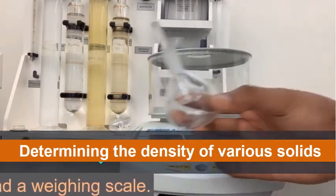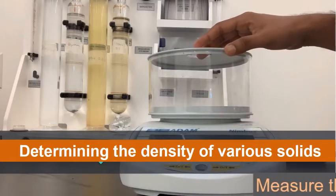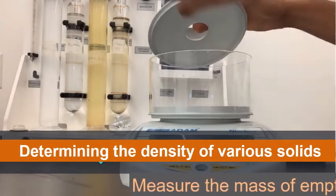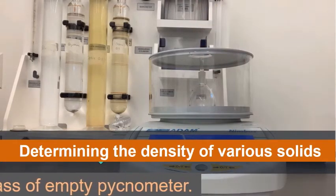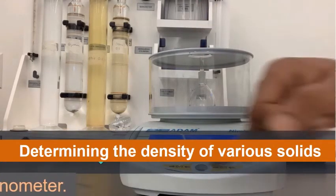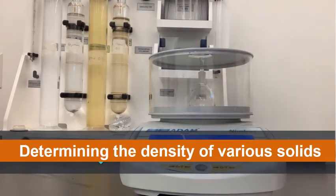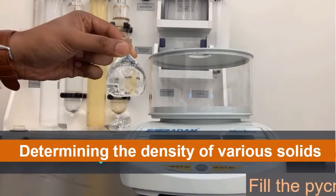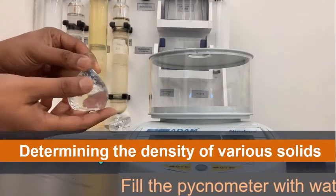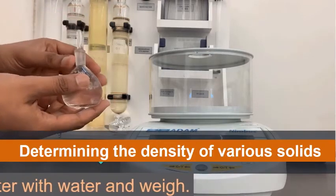First, we'll have to measure the mass using this weighing scale. Measure the mass of the empty pycnometer. So we'll make sure that before using the weighing scale, it is well calibrated. Then after we measure the mass of the empty pycnometer, we fill it with water and we close it using the lid.